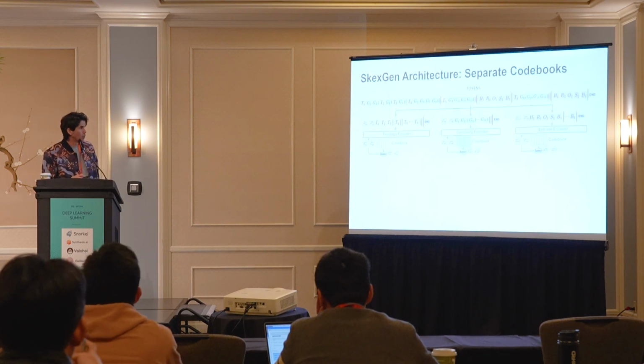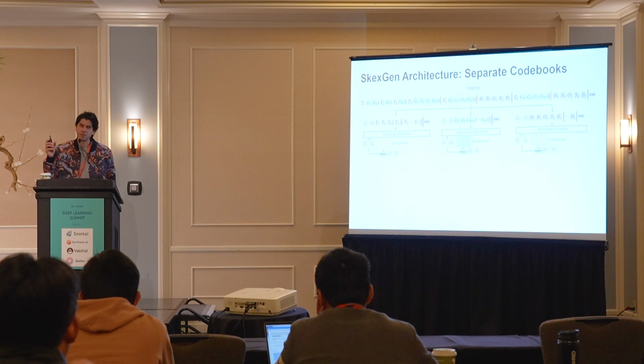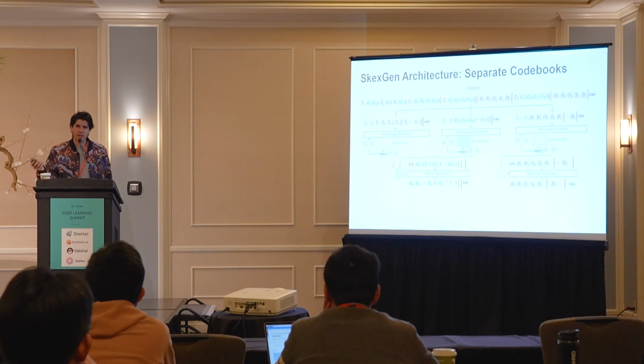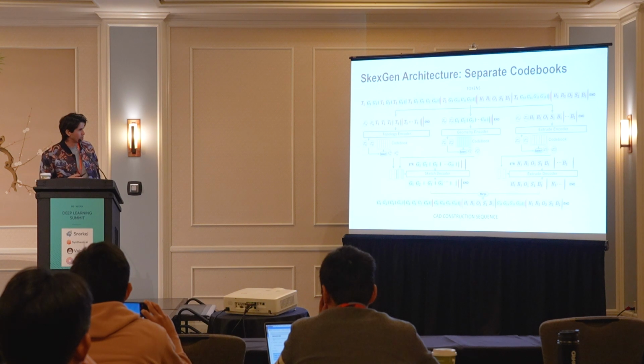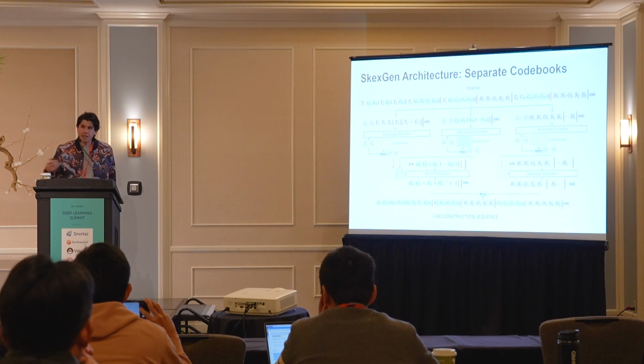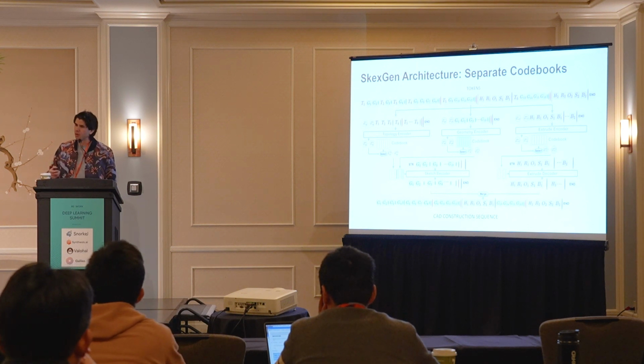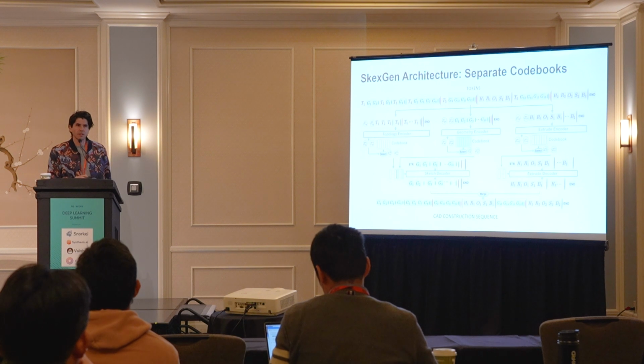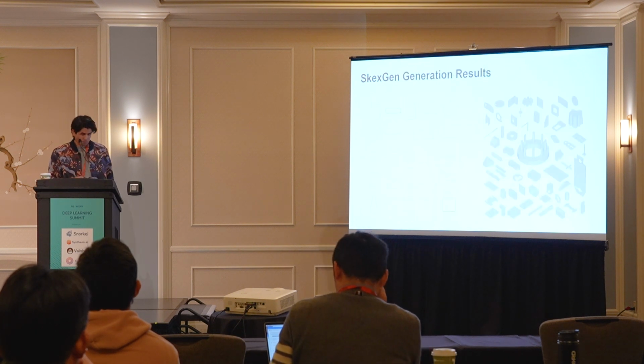One of the interesting things we do here is break apart into different encoders for topology tokens, geometry tokens, and extrude tokens, and use vector quantized codebooks as a way to have some interesting control. I won't go into too much detail, but you can look at the paper. At the end, what we get out is a construction sequence that we need a CAD engine to rerun, and that gives us the geometry coming out the back of it.